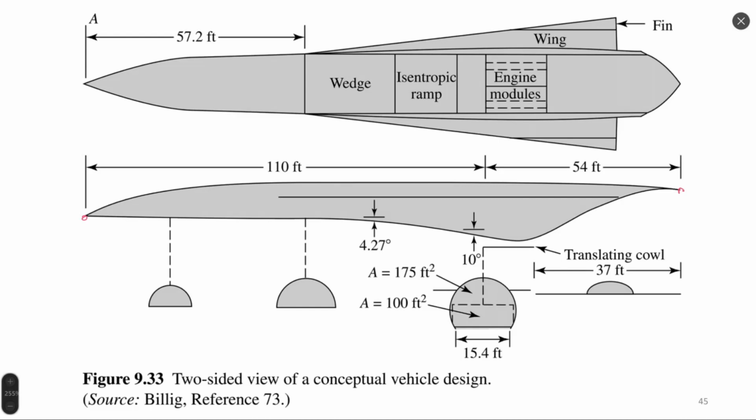In such a way, we can optimize or at least decrease the influence of the oblique shock wave. Oblique shock wave always exists, right? Here on the top, the oblique shock wave would probably be stronger, right? On the lower side, the oblique shock wave would be weaker, but would always exist. Even if this edge or bottom wall is parallel to flow, a shock wave will exist due to presence of the boundary layer.